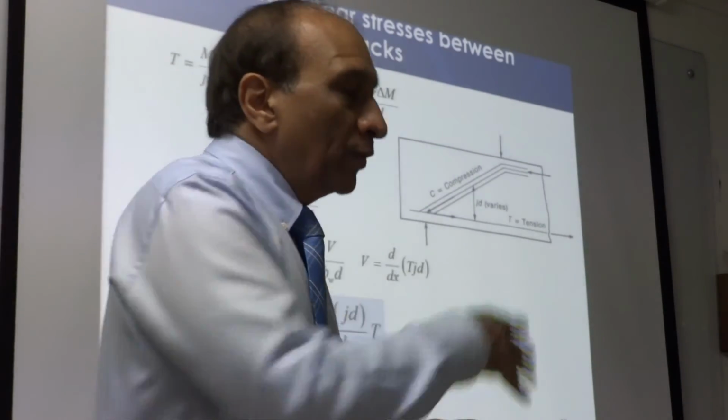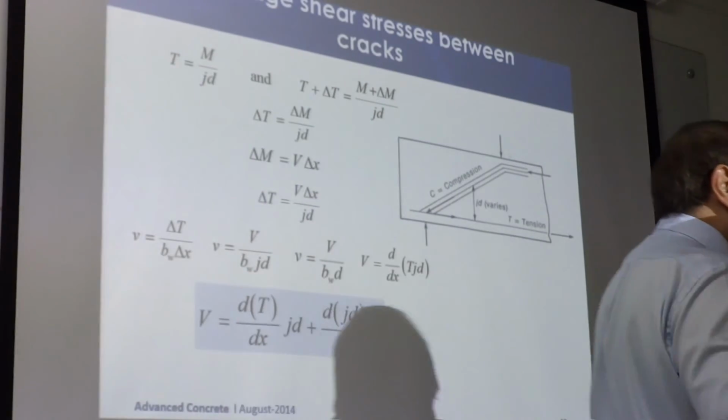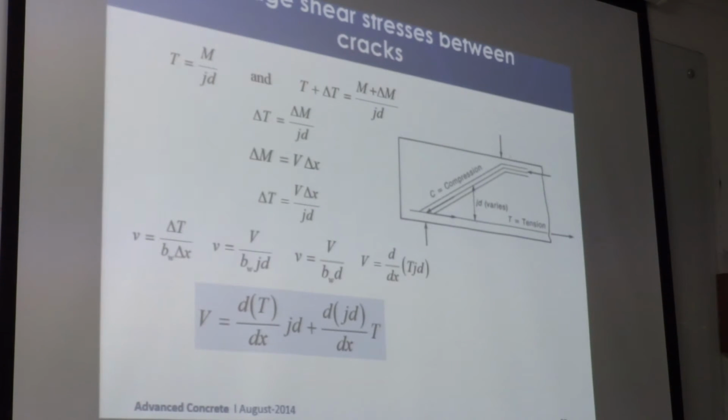If you provide horizontal reinforcement, that reinforcement will be mostly taking the tension coming from bending, so its shear effectiveness is less. But if you provide vertical reinforcement, bending has nothing to do with it, so all of that is available for shear. That's why it's more efficient to provide it along the shear than perpendicular to the shear. If there was pure shear, no bending, either direction would be fine. Right? So this gives you some idea of how the equations are derived and how the total capacity is calculated from the lever arm and capacity of the reinforcement. Okay.